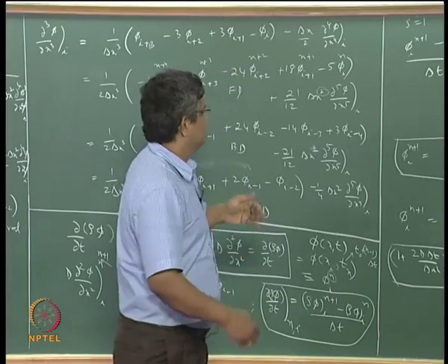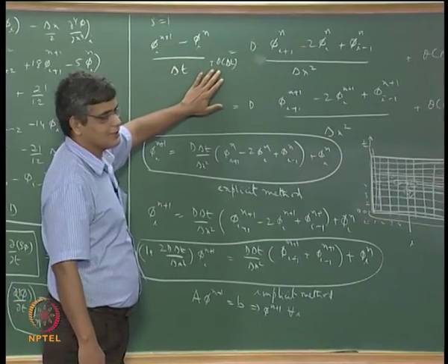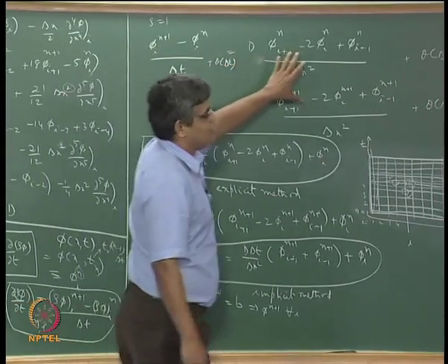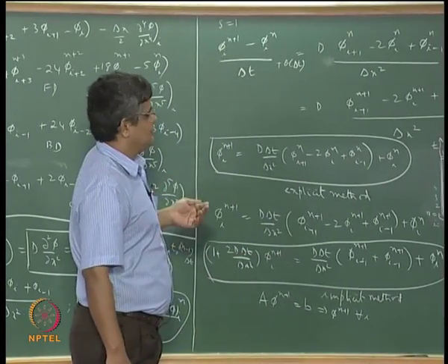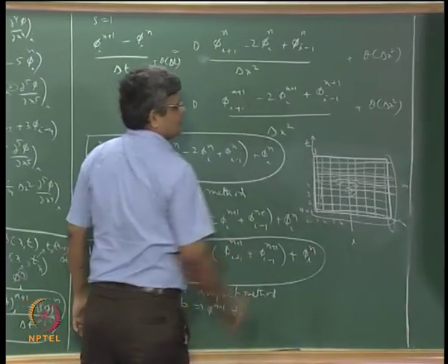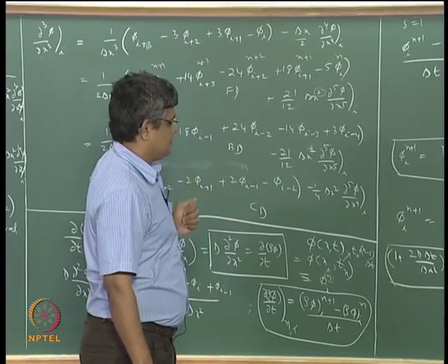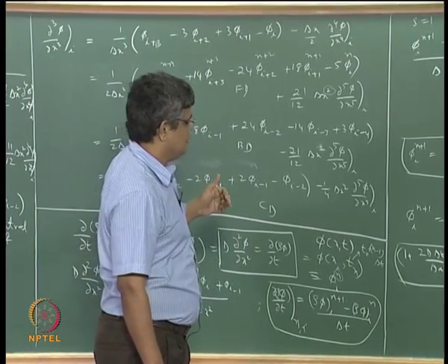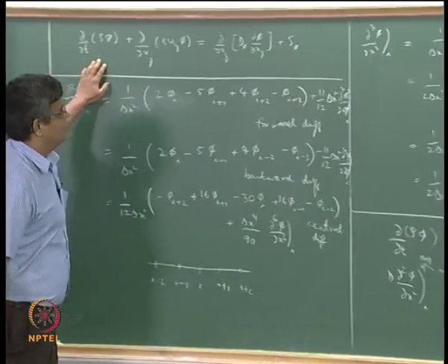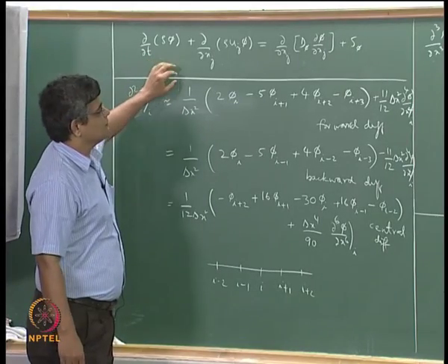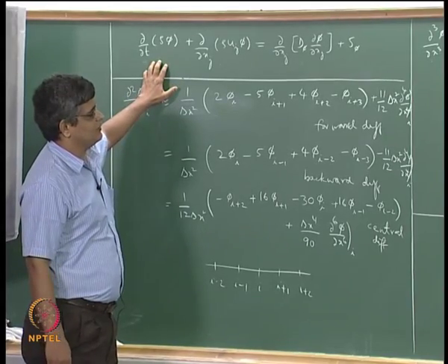Okay, so that's why we typically choose first order accurate or second order accurate schemes for the time derivative, but in space derivatives we can go for more accuracy, because these values are anyway known. Okay, so these are the considerations that we have to keep in mind when we look at a governing equation and use a finite difference method for the discretization of this particular equation.